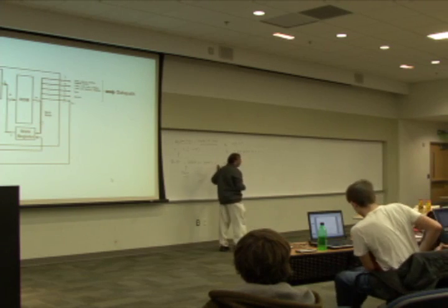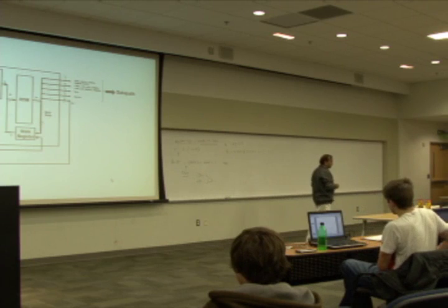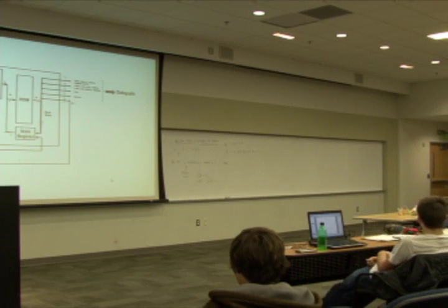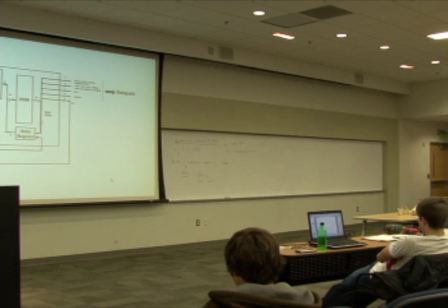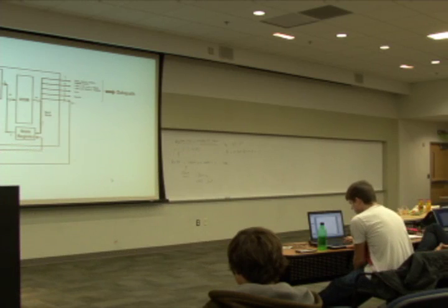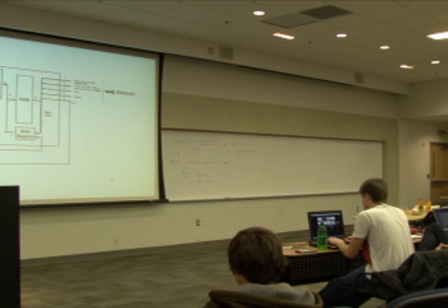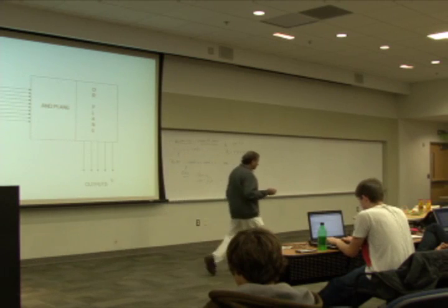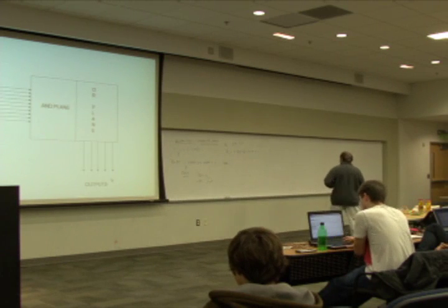And so every one of these control signals that you have to generate for your data path, you can represent as a sum of product form, and you can implement it using a combinational logic circuit. Okay, so this is one way of doing it, and so there is this dichotomy or alternatives available to you in terms of implementation, as either a microprogram control or a hardwired control, and it turns out that there are new things that are available in the market.